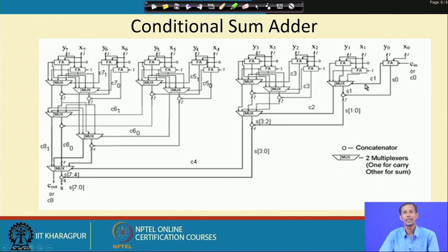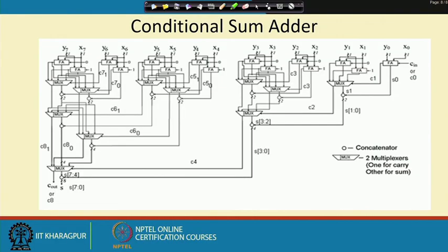In ripple carry addition or in any other addition, the previous stage generated carry affects the current stage, that means the sum and the carry both. Here, from the beginning we are calculating the values considering the carry input bit, which is of 1 bit, and since we are doing binary addition, it cannot go beyond 0 or 1. That is why we are pre-computing these values considering the carry input bit to be 0 and 1.